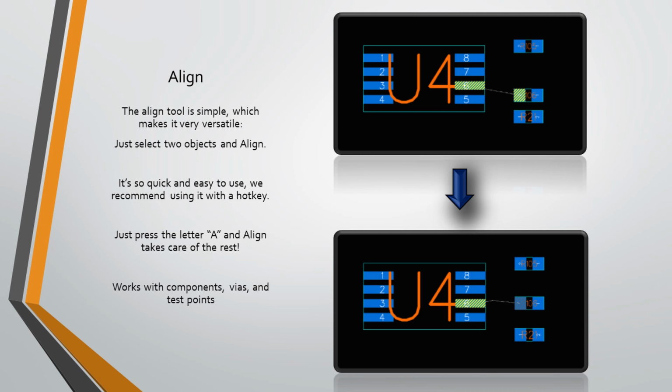traces. The Align tool is built on the premise that once the board layout is complete, the board does not know or care what placement grid the PCB designer used to place parts. In practice, the placement grid is completely irrelevant to the function of the board. What is important is that the traces take the shortest, most direct path from one pin to the next, with as few corners and jogs as possible. The Align tool makes it easier to accomplish this.